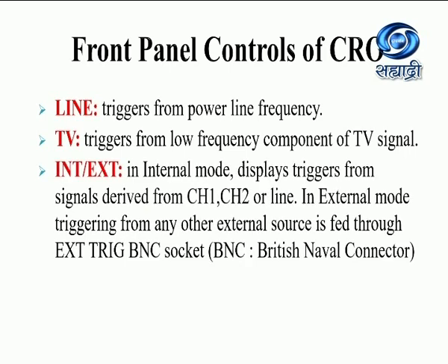Then again we have int and ext position. As I said, the internal mode displays the triggers from the signal derived from channel 1 and channel 2 or line. And in the external mode, triggering from any other external source is fed through the external trigger BNC socket. So in the internal position, we can apply the internal signal to the screen, and in the external position we can apply an external signal by using the external triggering BNC socket.